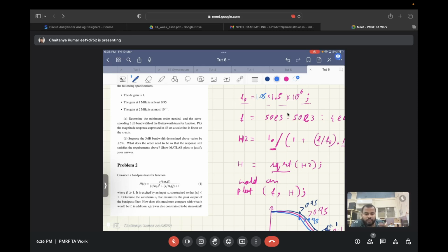What is the unique characteristic of a filter in time domain? In frequency domain, it's frequency response, right? In time domain, what is it? Correct, in time domain it's impulse response, right? So if there is some input to a filter, how will you find the output of that filter, given that you have the impulse response of that filter?